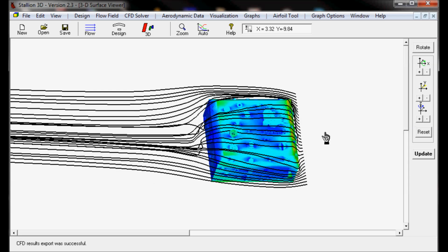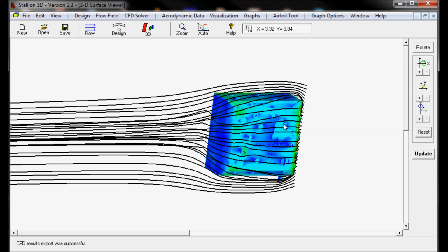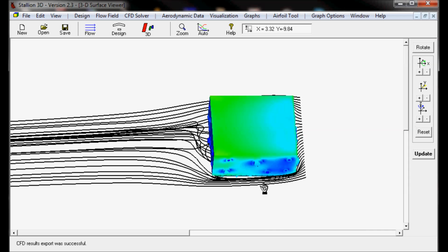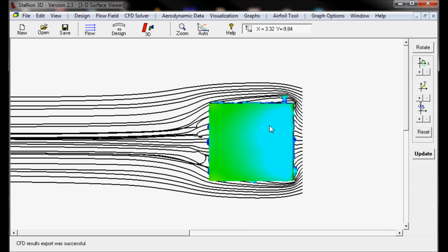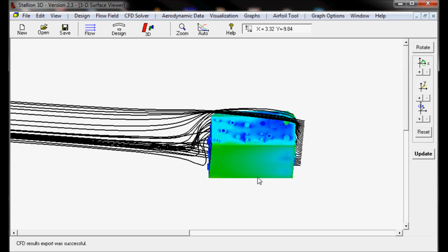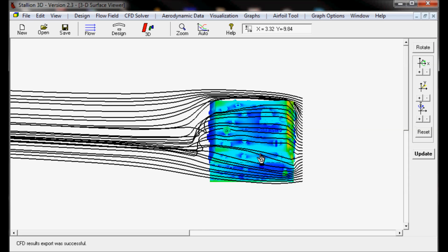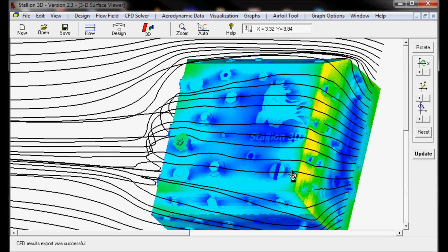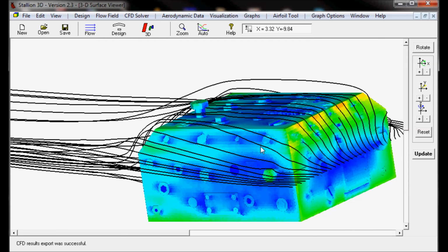and we are beginning to see, had we defeatured this geometry, it does make a big difference. Look at the bottom side. You can see a completely different flow field than at the top, where we have left all the geometry intact. We can see that this geometry leads to increased drag, and we can then deal with this in an engineering